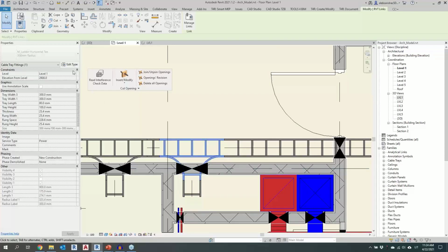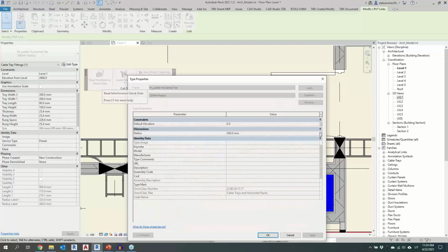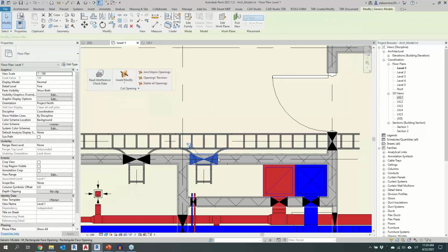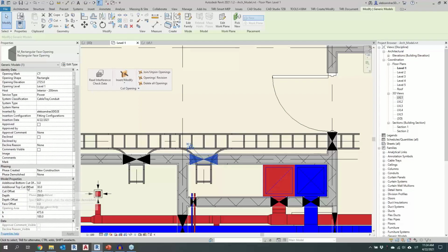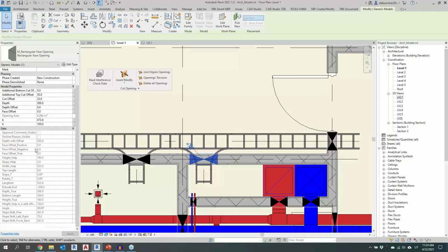And it just will go to show that our tool can copy not only instance parameters, which are actually easier to copy, but as well as that type parameters of elements. So to copy any of those parameters, we would need to create additional parameters in the openings themselves. And for these openings, fire rating parameter was already created as an example, and it copied value, but Omni class number was not copied. And how to do that?